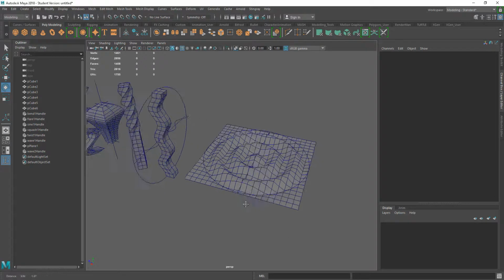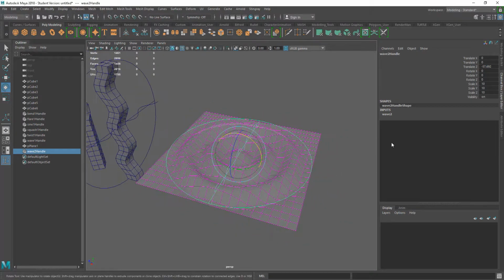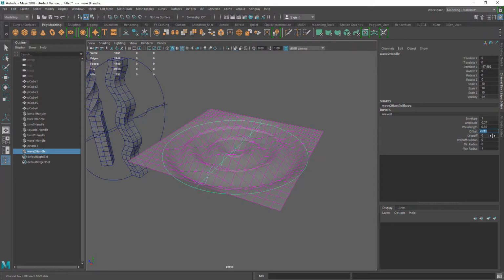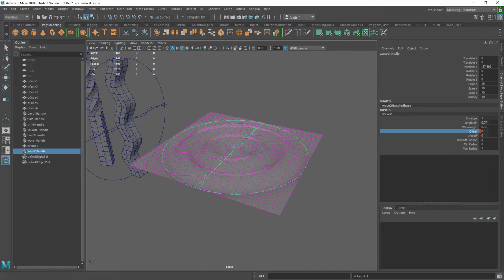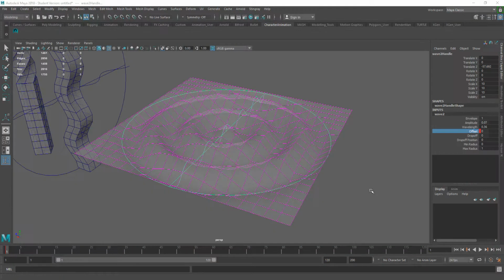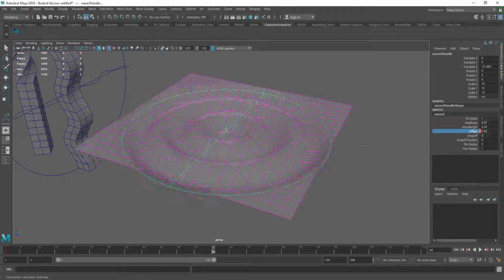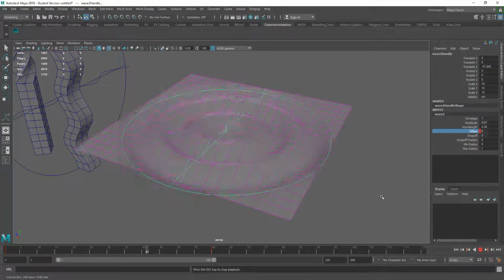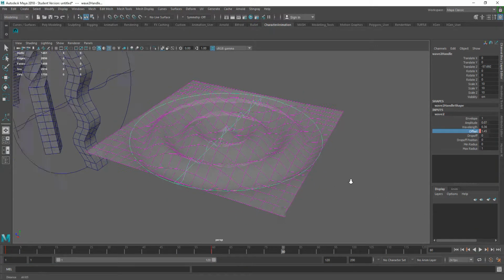So I was looking at this example here. I was just looking at creating this, changing the offset on this. So I could go in on this and actually, let's key selected. Just my modeling standard. Let's just go to my classic. Just have my timeline. Let's just move forward in the timeline and let's just change the offset. And again, right click, key selected. And there we have that animated. And we can do that with any of these properties within here as well.